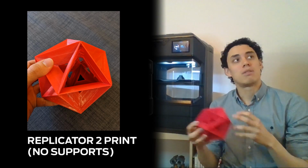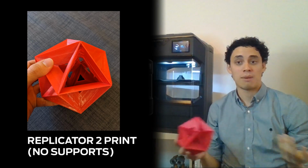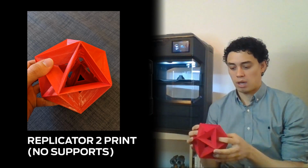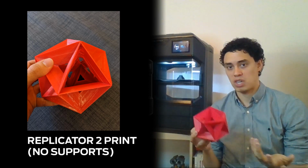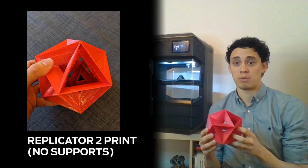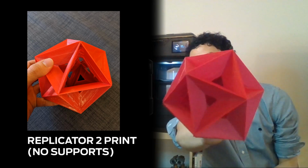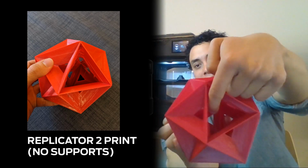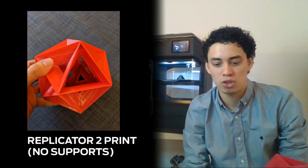So with more basic systems that only have a single extruder, you have to think about that compromise, right? Either using no supports or using breakaway supports, which in some shapes can be really hard to remove, right? It can be really tricky to remove the supports that come inside of that hollow structure. So imagine all of those tree-like branches inside of this part and me trying to pry them out. It's just going to be really hard.